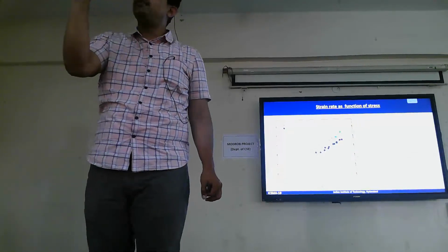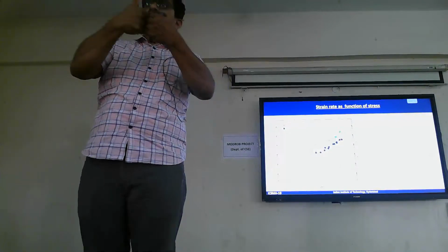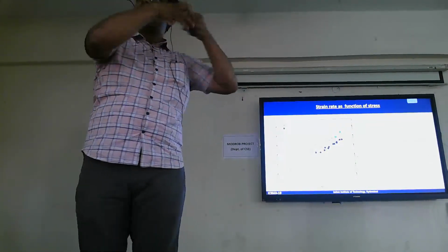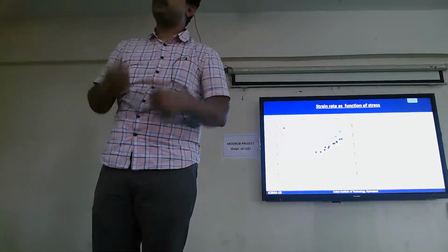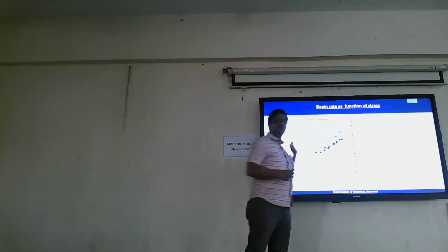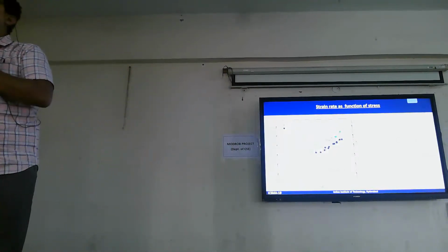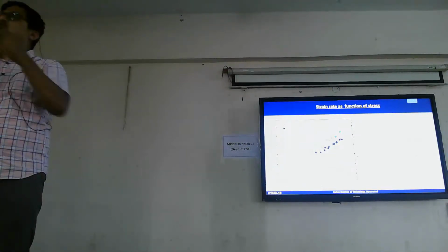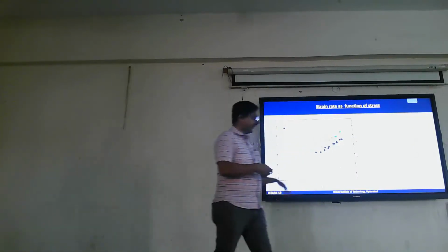Based on these values, we can tell which mechanism is controlling: dislocation climb, dislocation glide, Nabarro-Herring creep, which I discussed earlier, or diffusion along the grain boundary, which is called Coble creep. So here my n varies from 3 to 4, 5 almost. n equal to 3 is dislocation glide controlled creep. Just believe me. n equal to 5 is basically dislocation climb controlling, which is the slowest process. But my n is changing from 3 to 4.5.